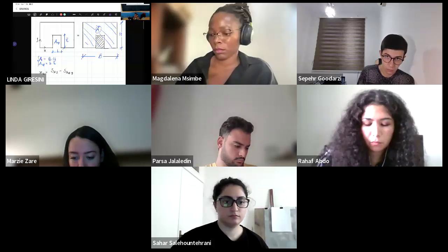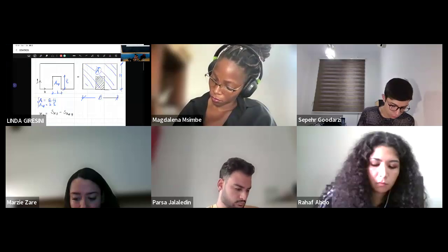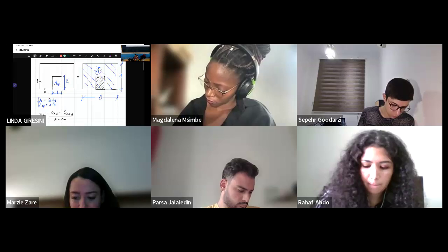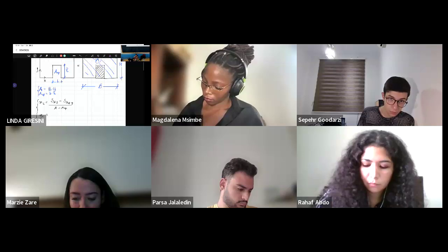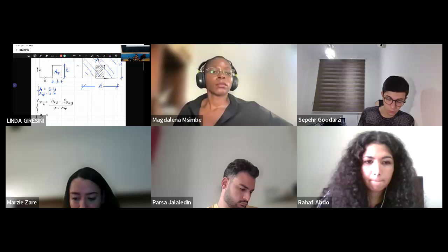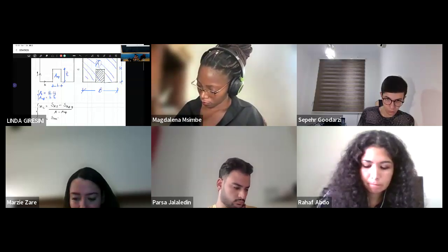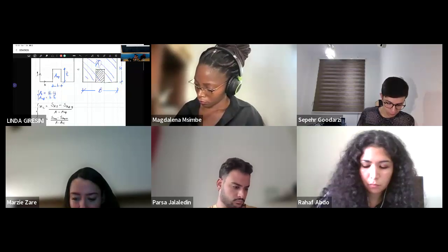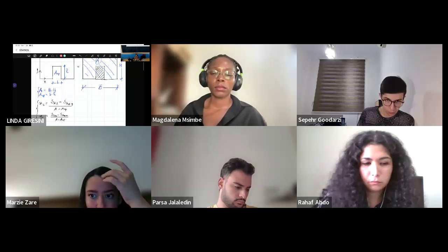So the Y and the X-axis are already there, divided by what? A minus A opening. Exactly. Because you are subtracting that opening. So that opening is removed from the total area. So again, for YC, you have SAX minus SA opening X. It's just a matter of changing the letters. And the denominator is the same. So it is A minus A opening. Clear?